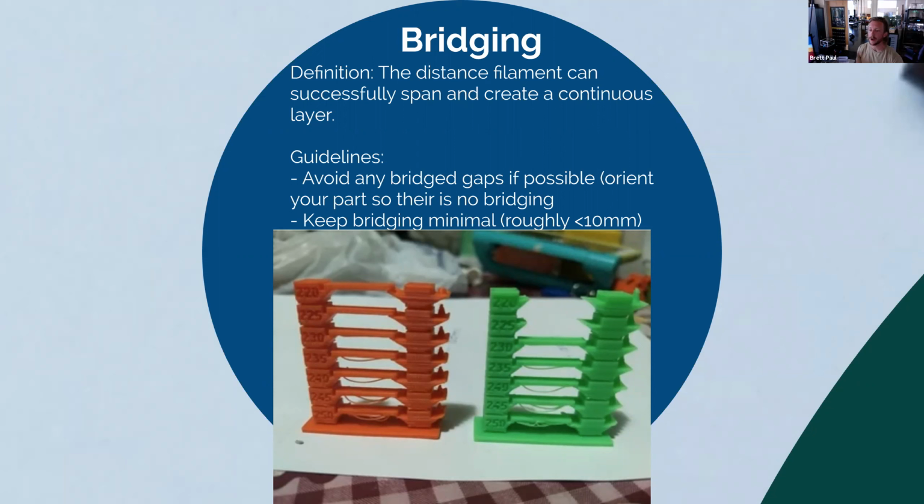So your nozzle to bed error, let's call it, will be the largest at the sides. And so if you build in a buffer zone, let's say your build volume is a little bit smaller, you're hedging against that error on the outside. Okay. Thanks. And again, as I become more familiar with these particular printers, that guideline would maybe expand or loosen a little bit. Yeah, makes sense.